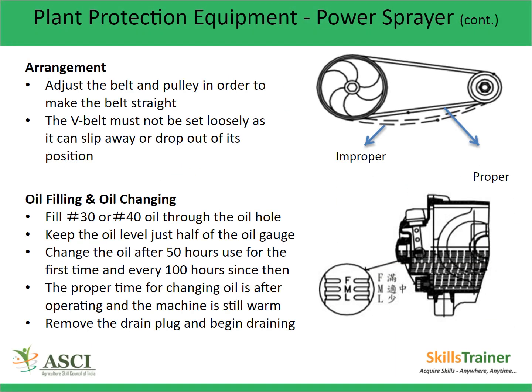Arrangement. Adjust the belt and pulley in order to make the belt straight. The V-belt must not be set loosely as it can slip away or drop out of its position.